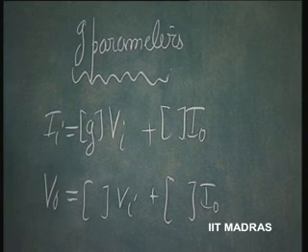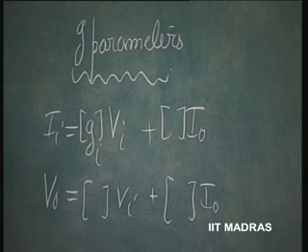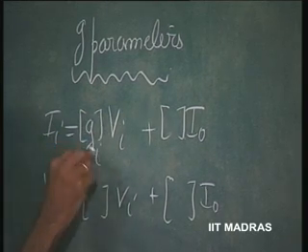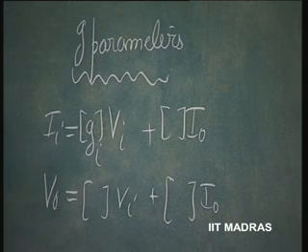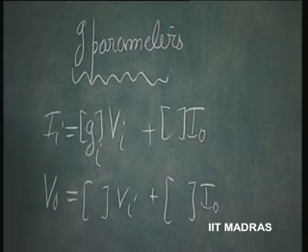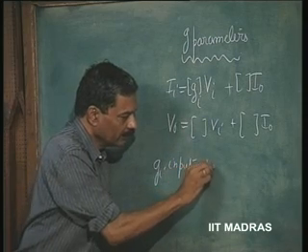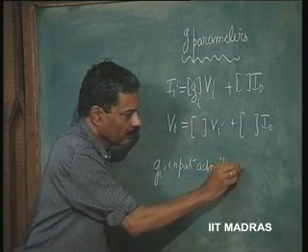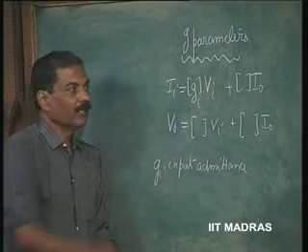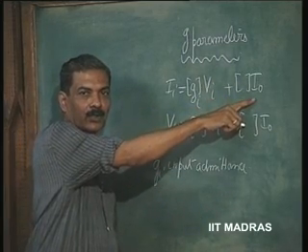suffix is Gi. This game is now very clear to you, right? You can yourself put down those suffixes. So, Gi indicating what? Self admittance now. So, this is an admittance, input admittance, when I naught is 0, that means open circuit output.